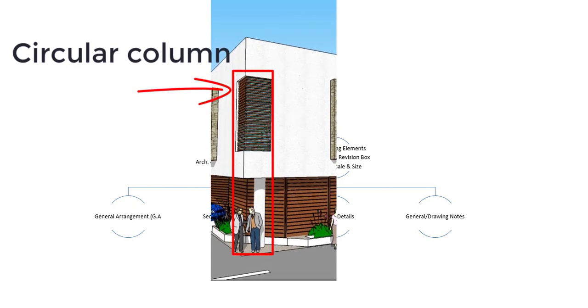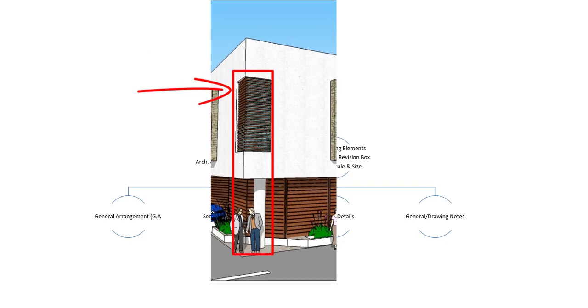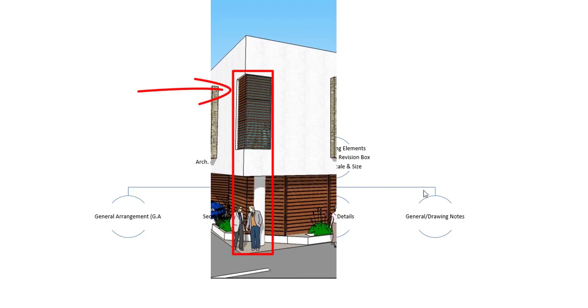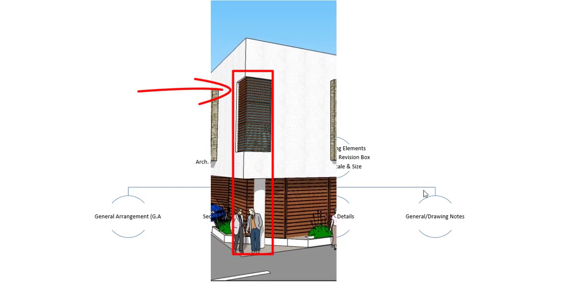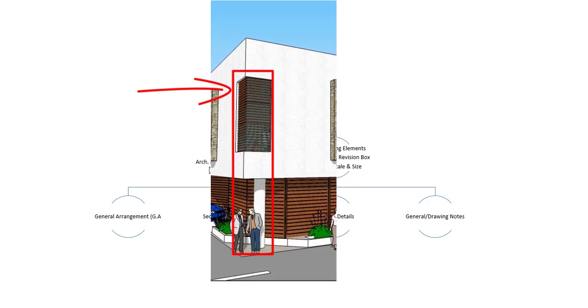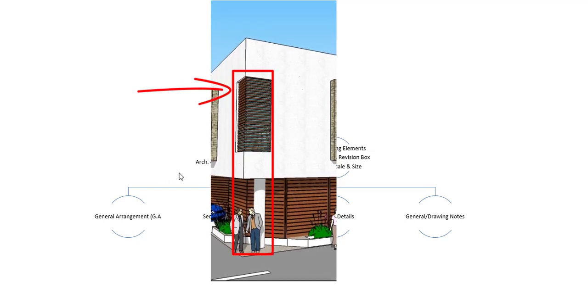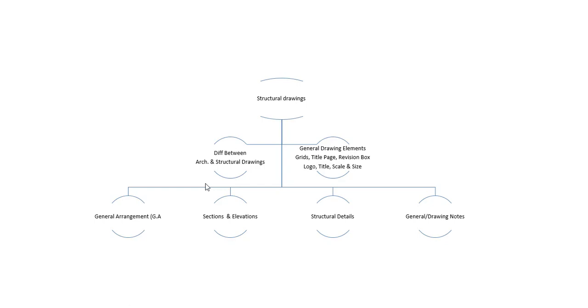So information such as dimensions, either length, width or diameter in case of a circular column, and appearance, paint color if it's a painted finish, or details on the materials if cladding is required. All this information is related to the architectural part. Now for the same column, if we discuss the structural drawings, the strength and stiffness characteristics of the column are the most important information.